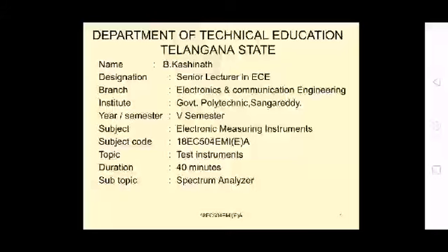In the previous class we learned about the total harmonic distortion meter or distortion factor meter. In that, we measure the total harmonic distortion by using the Wien bridge method. The distortion factor meter with the Wien bridge method acts as a rejection amplifier, which will suppress the fundamental component of your input signal, and pass all the harmonics of your input signal. In that block diagram we explained that you will be having the input, and you will be having the impedance converter.